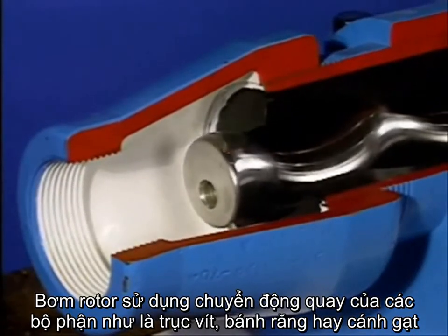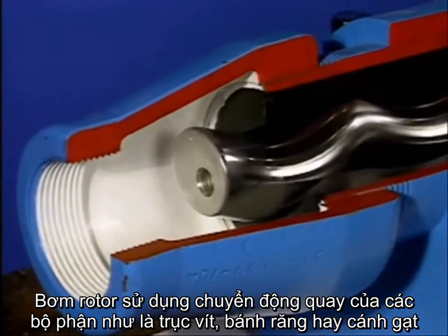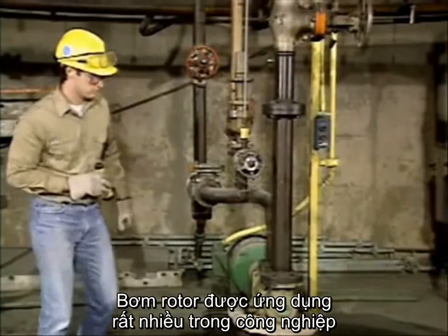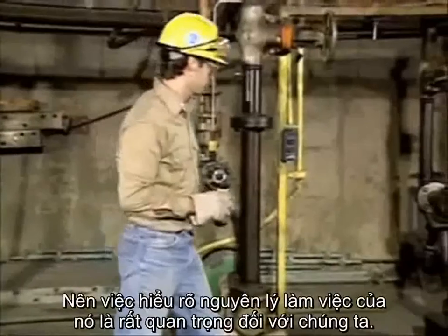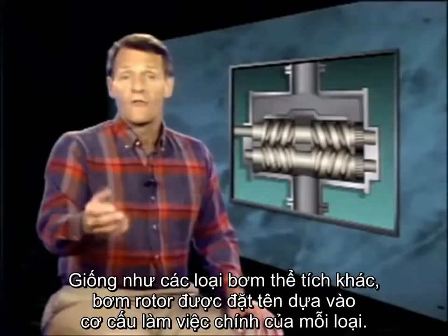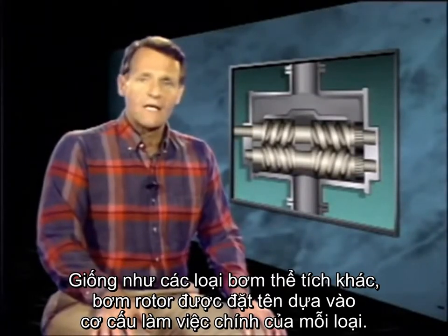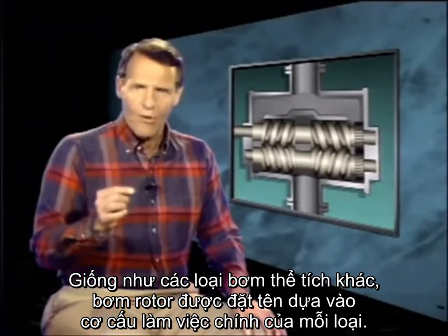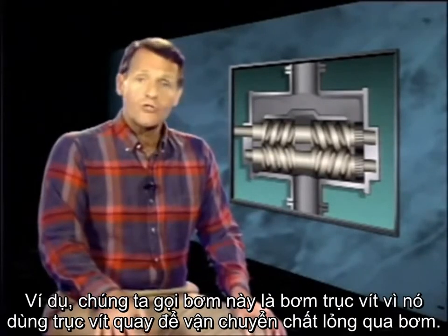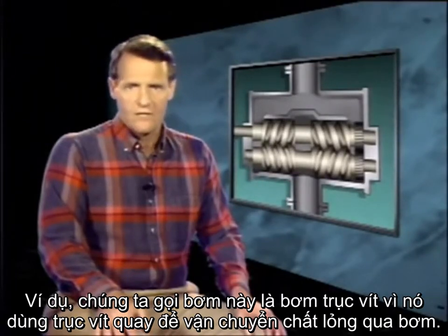Rotary pumps use the rotating motion of components like screws, gears, and vanes to move processed liquid. Since rotary pumps are common to many industrial applications, it's important for operators to understand how they work. Like other types of positive displacement pumps, rotary pumps are commonly named according to the type of component that moves liquid. For example, some rotary pumps are called screw pumps because they use screw-like components to move liquid.